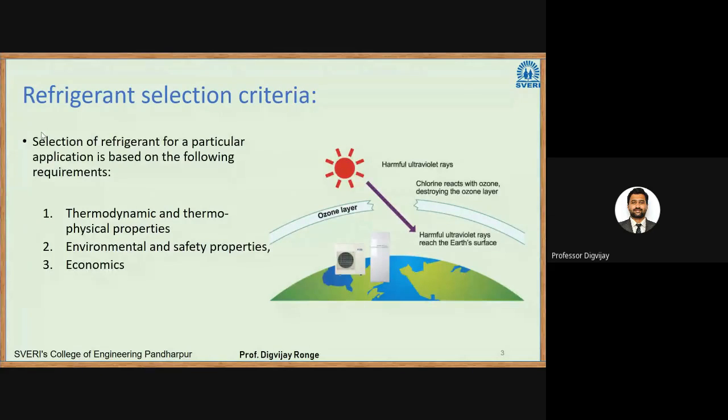Okay, so ASHRAE is providing standards in the safety of refrigerants. In the last lecture I told you, ASHRAE standard 15 provides guidelines for handling of refrigerants, and ASHRAE standard 34 gives guidelines on the nomenclature of refrigerants. So how these refrigerants will be classified and how this numbering works. Like we have R11, R12, R22. How this numbering is given, that is specified by ASHRAE standard 34.